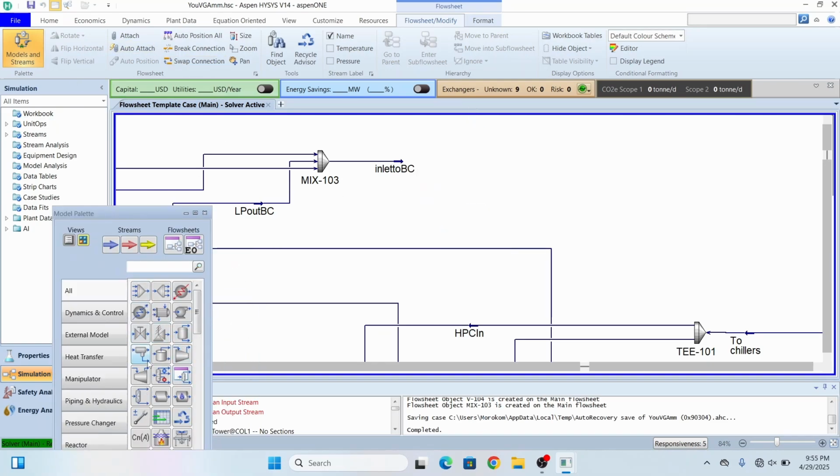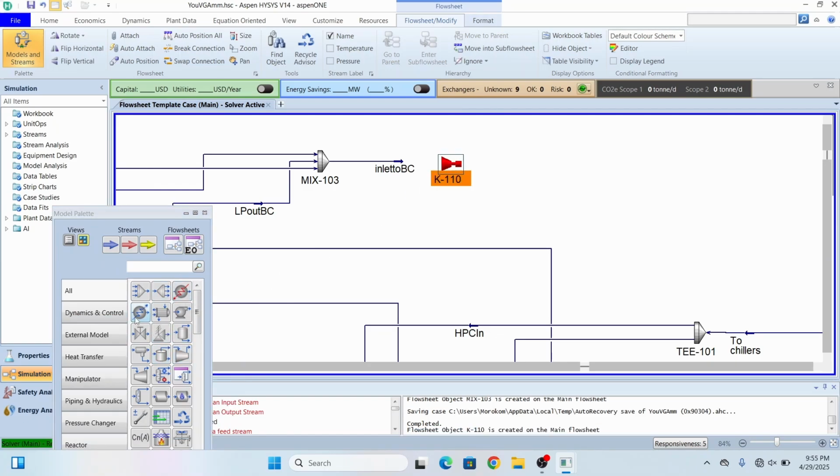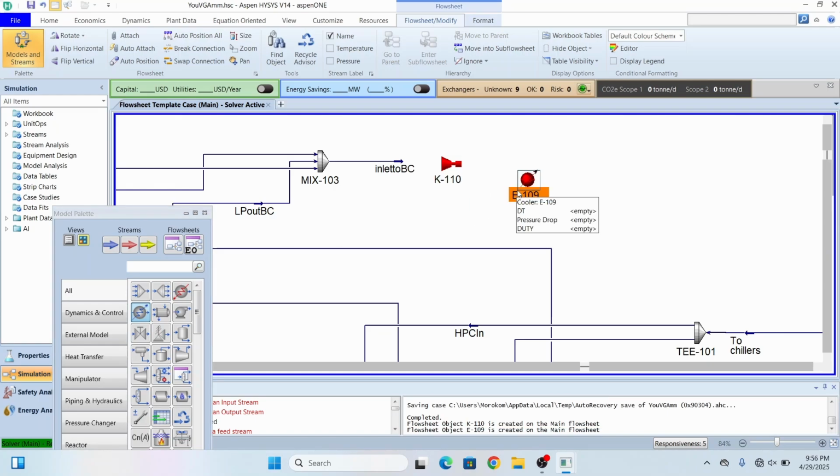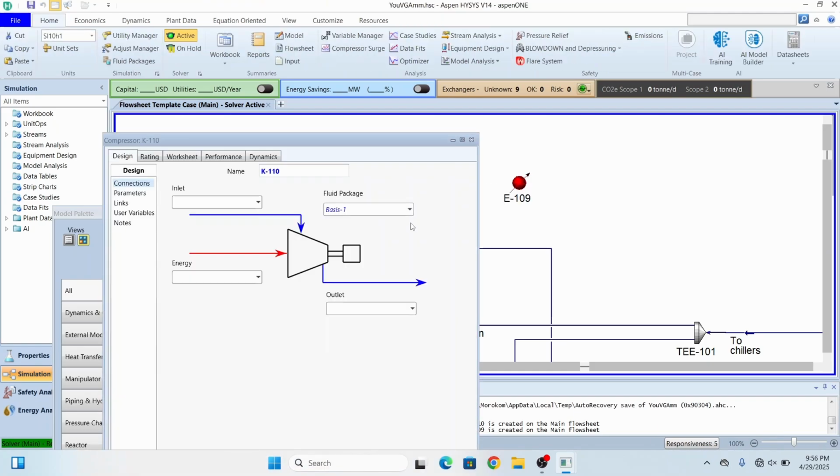Here, first of all, I will take my first compressor. That will be my interstage cooler heater. I am taking three compressors with a compression ratio of 2.96, and we will see whether after the third compressor stage my pressure becomes equal to 25 kg or not. I will simulate this first stage only, and then I will increase the speed of the video to simulate the other two compressors.